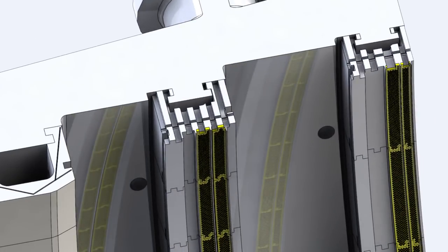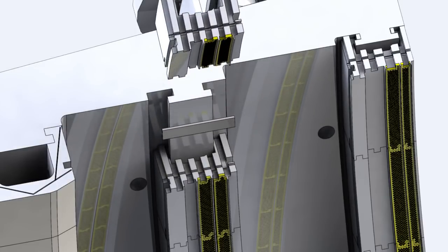The second and third stage shrouds have teeth that mate with teeth on the tip of the second and third stage buckets. This labyrinth seal minimizes tip leakage. For better tip clearance, a honeycomb seal is integrated on the second and third stage shrouds. This honeycomb is relatively soft material. The cutter teeth on the tip of the second and the third stage buckets open a slot on the honeycomb seal without any material transferred, providing tighter clearances to improve the unit efficiency. Shrouds of the last two stages are sealed by interconnecting tongues and grooves and by key seals.